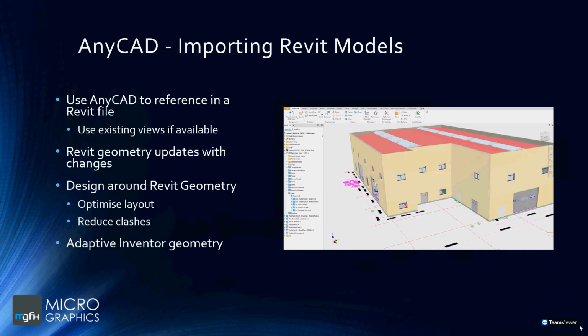So, as I mentioned, the AnyCAD option in Inventor, or the importing in Inventor, is a very important step in that. The first step is that AnyCAD file. And it will be essentially for the architect. The first step will be for the architect or Revit user to generate a view within Revit that contains the area required for the equipment to be designed in.